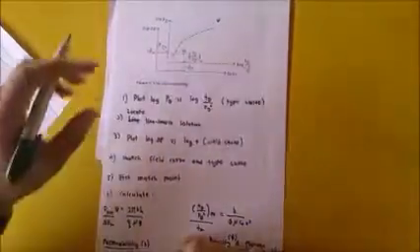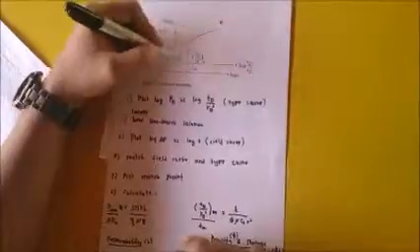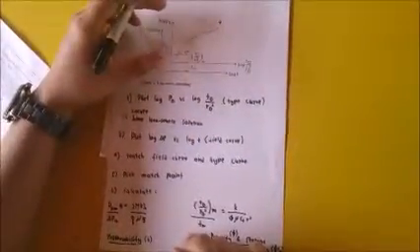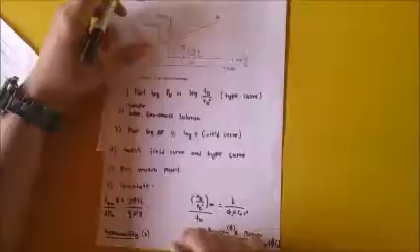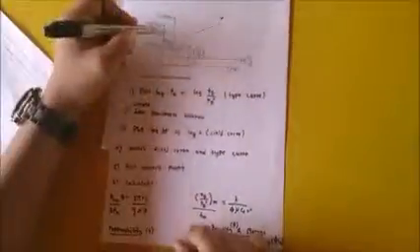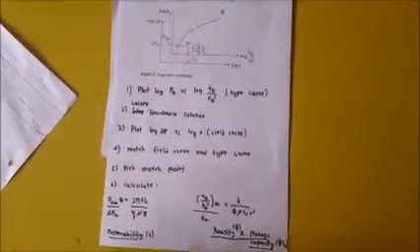The next step is we match the field curve and the type curve. This one we call the type curve, and this one we call the field curve. Then we match these two curves and pick a match point, denoted by M, PDM, delta PM. And when we get all these match points, we can proceed to calculate permeability, porosity, and storage capacity.